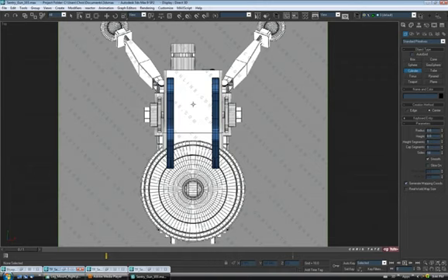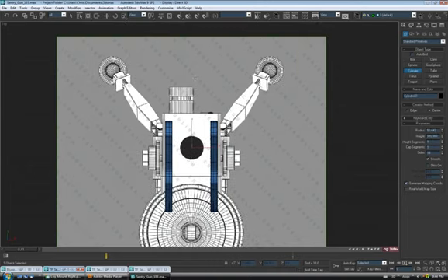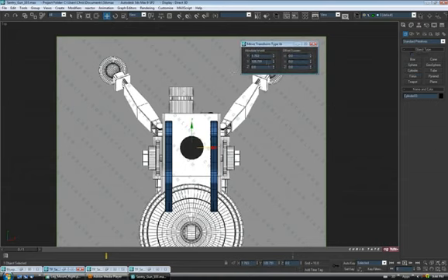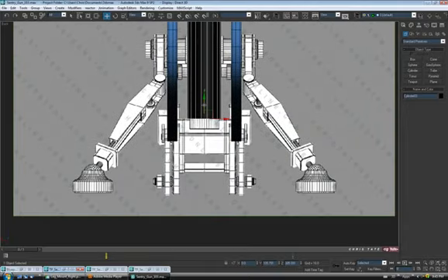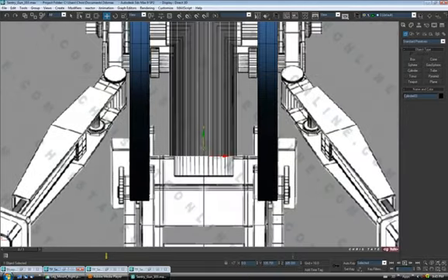Yeah, I'm just going to drag one out here and kind of guess at the radius because I can't see it. Alright, so just get one in there. Let's also center it on X. So I'm just going to right click the move tool, right click the X spinner, and we'll jump into the front view and just move it up into position. Right, let's zoom in here. I'm just going to go into X-ray mode, Alt X. Right, just move that down.